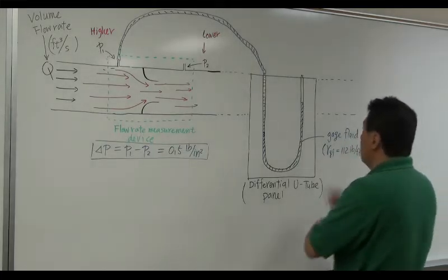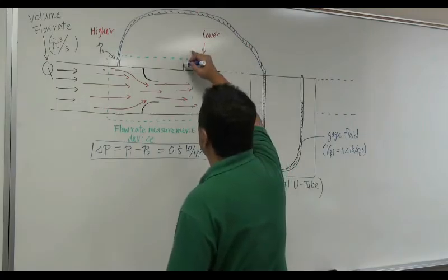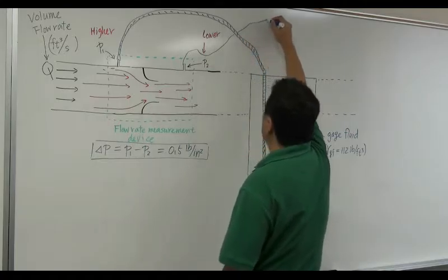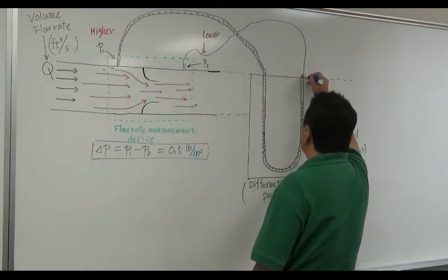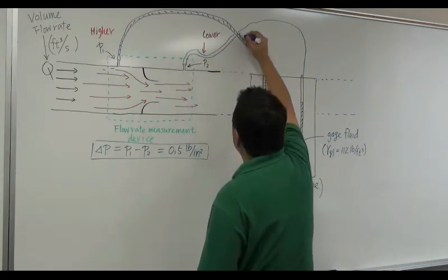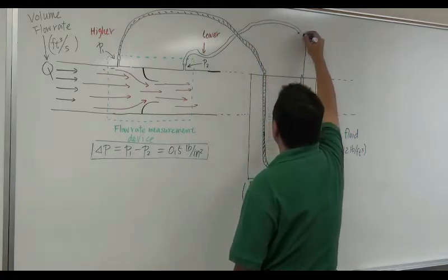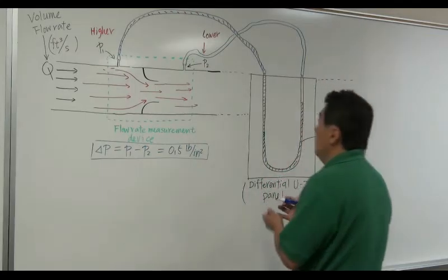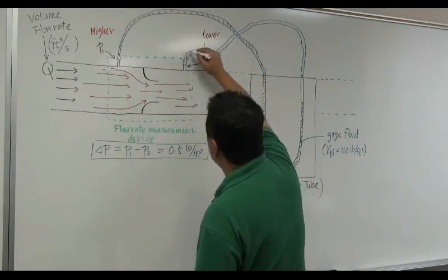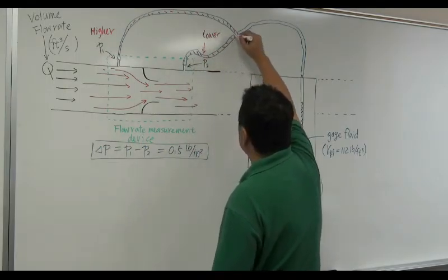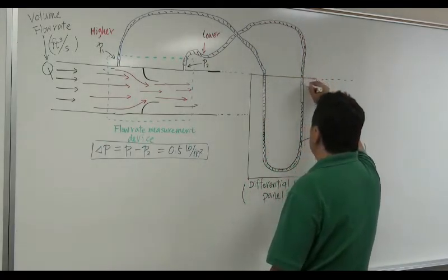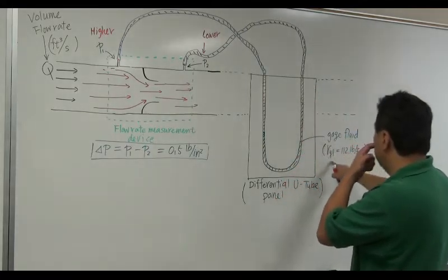Now, the right hand side leg is of course connected to this pressure tap P2. So you're going to again use the Tygon tube. Connect up this pressure tap to here. Now obviously, because water is flowing inside, naturally you are going to introduce water into the tube also. So this tube is filled up with water until it meets this gauge fluid.